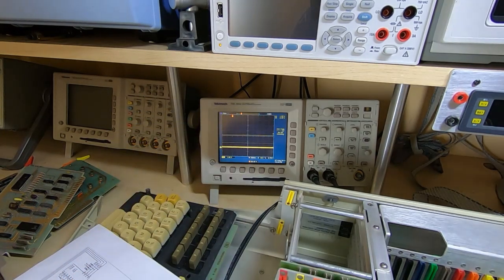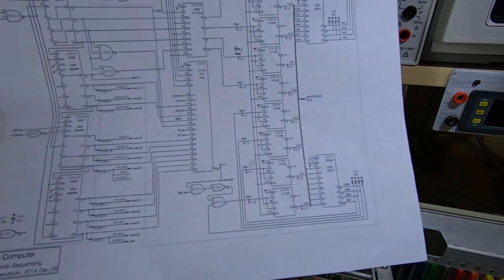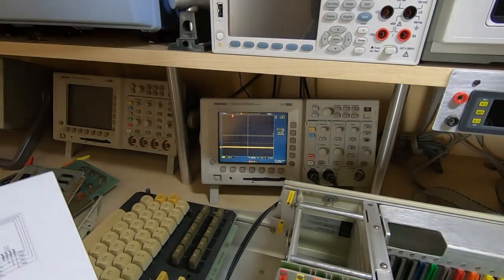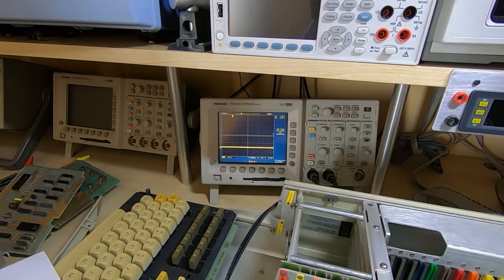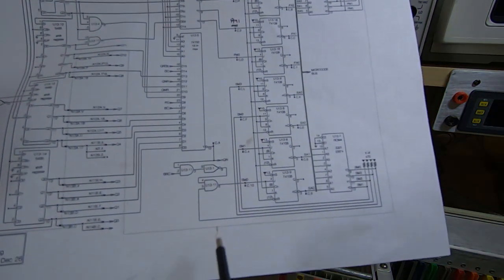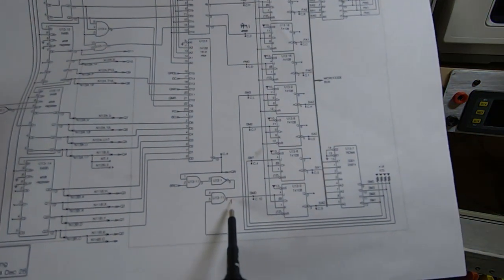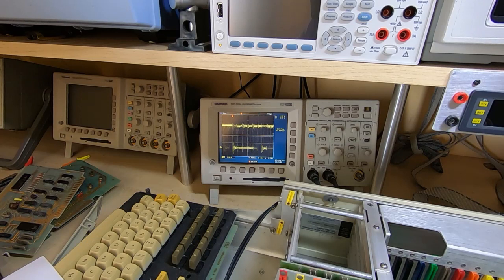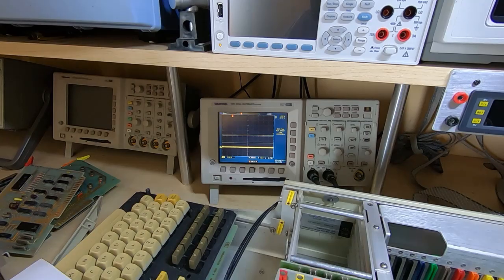So what we'll do now is look at the signals on the scope, see if they now look as they should. So looking at the same points, we'll check pin 3 first and see if that's switching the way it should be. And if you remember before, it was just kind of stuck halfway. As you can see on the scope, that's now switching the way it should. And then the output of the other gate on the same IC was also kind of stuck halfway. That's pin 6. So we'll look at that. And again, that's now switching as it should. So we'll look back at the logic analyzer and see if we've improved things at all, and if the microcode can get any further than it did last time.